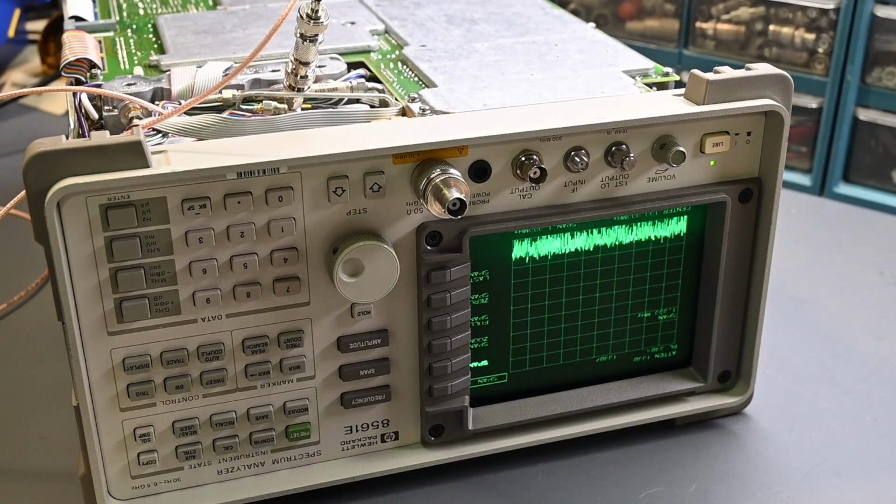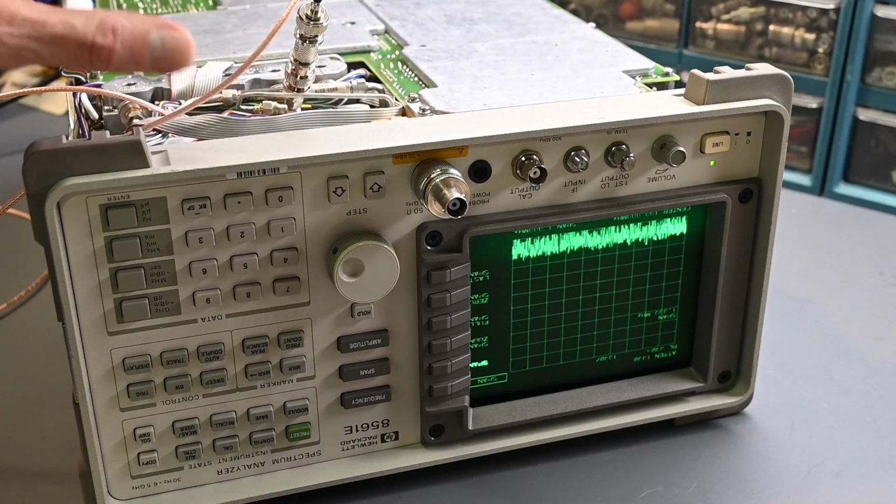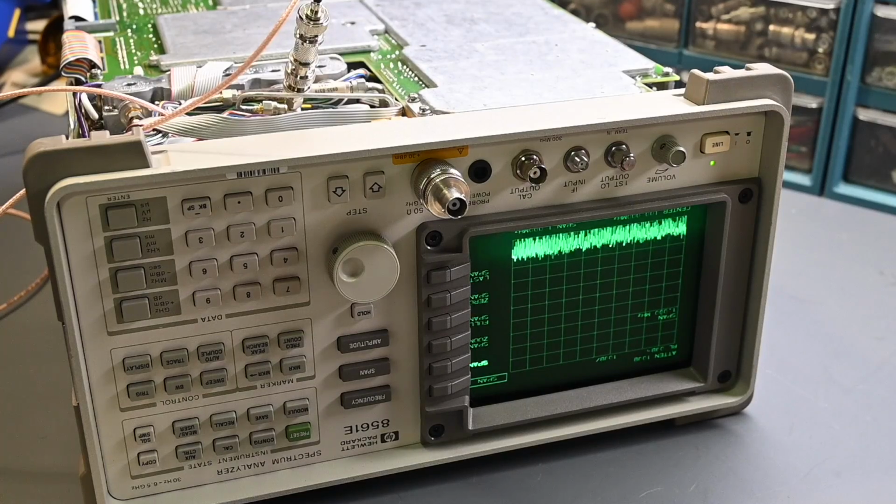So I have the output on the signal generator set to minus 40 dBm, a nice, safe, low level. Again, we don't want to increase it too high because we're after the attenuator and everything here. So I think minus 40 dBm should be perfectly fine. So it's set to 1 megahertz. Let me switch this on right there. So 1 megahertz, minus 40 dBm. So we're good to go there.